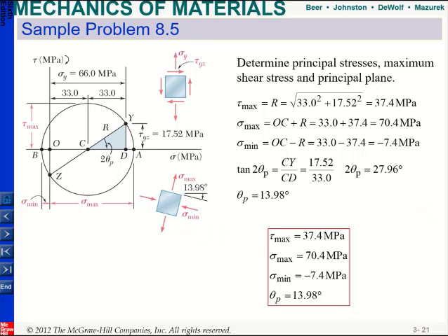Alright, so again, this is how it looks. You have sigma y, which is your normal stress, and this is your shear stress, and in this case your sigma z is equal to 0. So this is why your average is just equal to sigma y over 2. The directions might change. Sometimes you might even have tau yx. But in this question you have tau yz, and this direction will be your z direction, and you don't have any normal stress along the z direction. So that's why your average is just half of your sigma y.